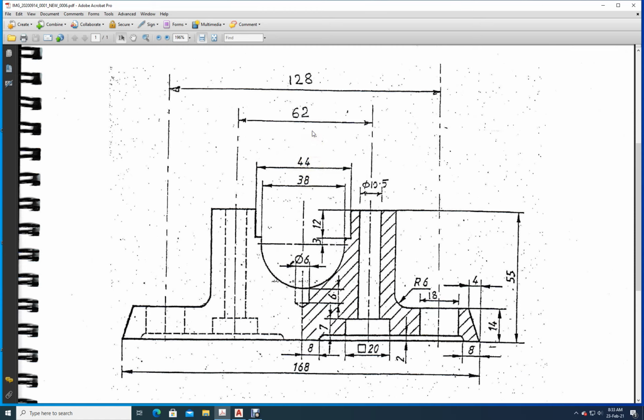So in this drawing what I will do is I will create different layers. One layer will be there, that is the default layer. Let us use that one to draw the picture. Coming to dimensions, we will create a layer for dimensions, and then we will create another layer for the axis. Okay, so let us create these layers first, and then we will go ahead with the drawing as we proceed.